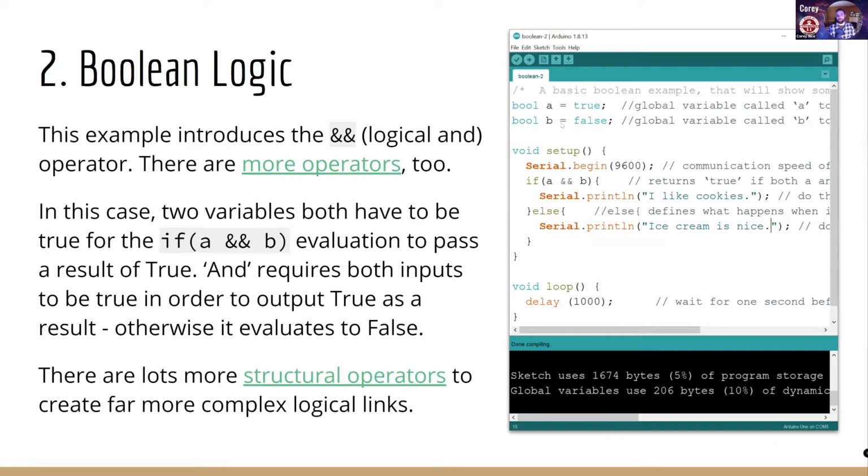One of those is where you'd consider something with a couple different variables. Like here's a variable and it's a Boolean type variable, so these values can only be true or false. And true and false have synonyms, like true is the same as a 1, or the same as having a high voltage of 5 volts on an Arduino. And false is the same as a 0, or the same as having 0 volts or being at ground on an Arduino. And so having Booleans that you can play with is a really useful tool inside of an Arduino sketch.